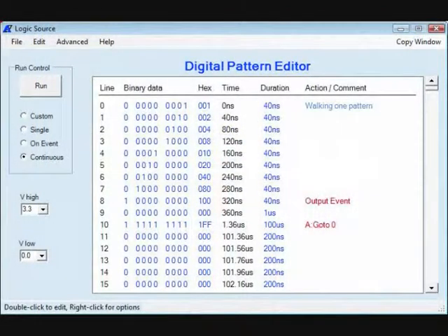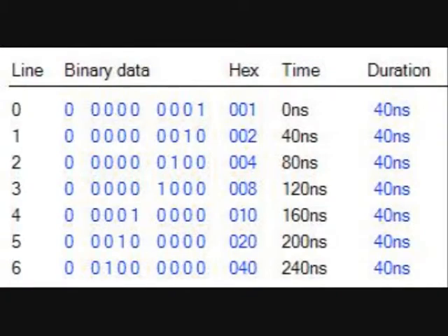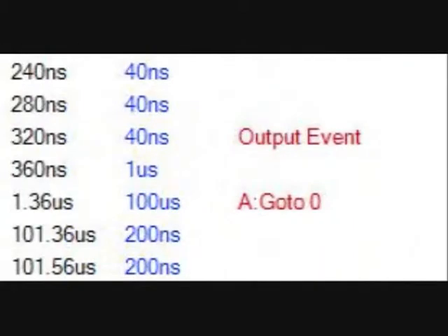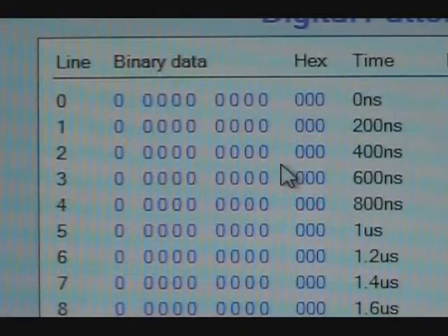The Logic Source tool generates digital outputs defined by user-programmed vectors. Each vector includes 9 bits and a settable duration value that can range from 16 nanoseconds to 33 milliseconds. Each vector may also include a command that loops the execution or synchronizes execution with other tools or the user circuit. The Logic Source user interface provides an easy-to-use digital editor.